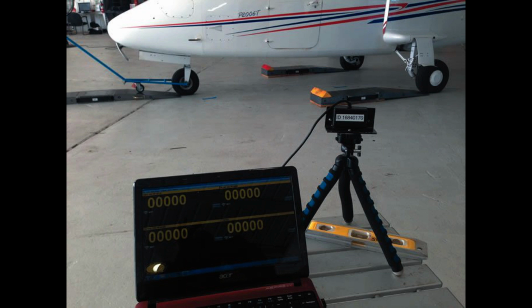Equipment list. All of the required equipment must be properly installed, and there should be no equipment installed that is not included in the equipment list. If such equipment is installed, the weight and balance record must be corrected to indicate it. Ballast. All required permanent ballasts must be properly secured in place. All temporary ballasts must be removed.